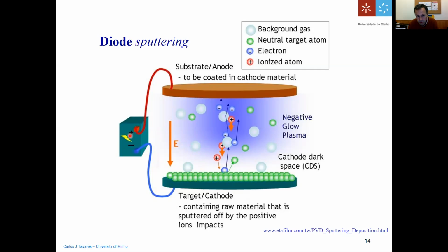So in one polarity, when it's alternating, in the negative polarity, you will attract argon ions. Okay, and on the positive polarity, you will deflect them, you will repulse them. And by doing this, you can also make some impact in reducing the possibility for oxygen atoms to be adsorbed on the surface and to poison your target, literally.